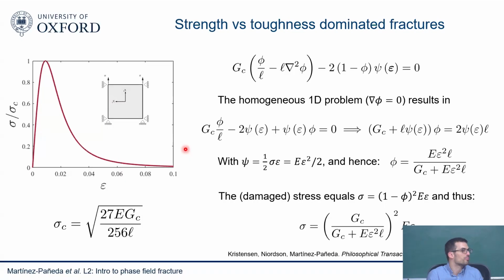And this is what we normally call the fracture process zone in materials. We know that the damage is spread over a certain region. So that length scale, since it tells me where my damage variable spans, basically tells me how thick my interface region should be, how big my fracture process zone is. So it must be a material property because, for example, very brittle materials have a very small fracture process zone. Metals have a very large fracture process zone. Damage is occurring over a long area, whereas in brittle materials, it's a very small area where damage is occurring. And conceptually, it comes as natural to think that it must be a material property, that it must have a size that is related to the material.